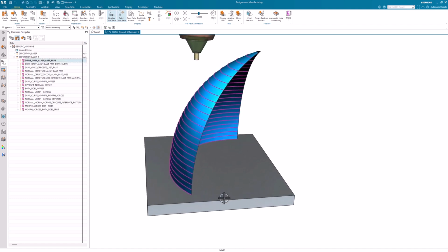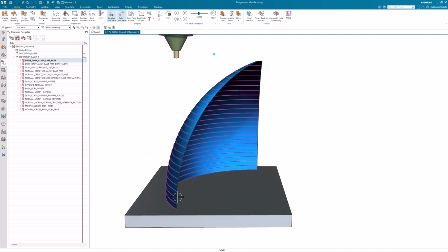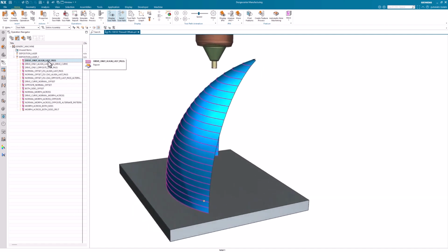Previously, programmers could only make one bead width on thinwall faces. If they wished for a thicker part, they had to offset the face, create multiple operations for each offset face, then merge the operations together. Enhancements to 3D Freeform Thinwall Buildup create an improved user experience by automating this process, so the user is not required to create additional faces and operations to get a thicker part.